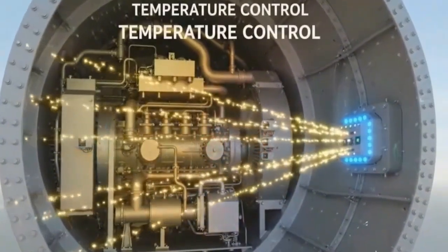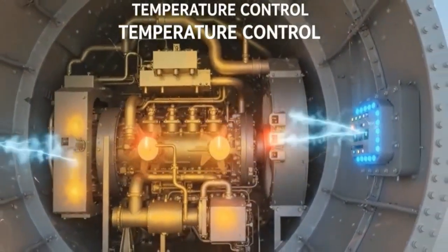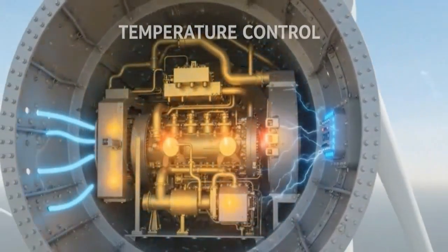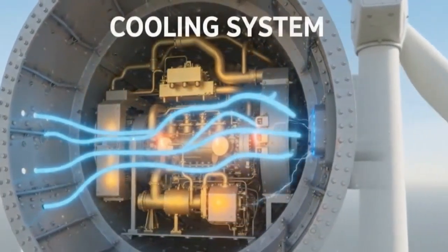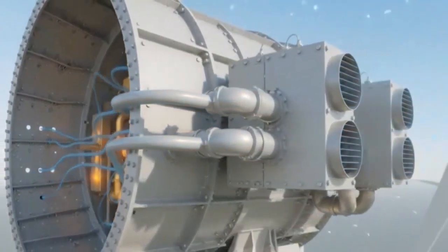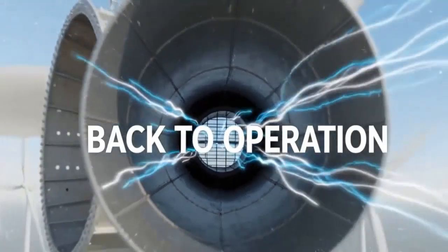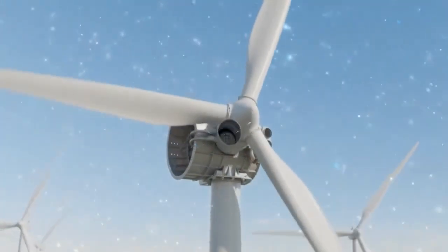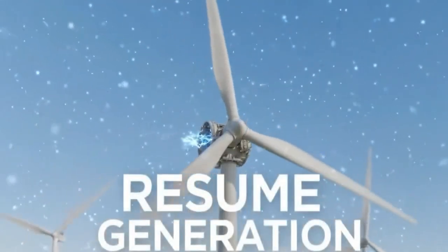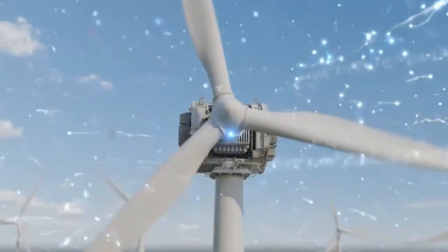From the tower base, electricity passes through the transformer and cables into the wind farm electrical network. At the substation, power from many turbines is collected, controlled, and prepared for transmission. The transformer increases voltage, helping electricity travel long distances more efficiently with lower energy loss.